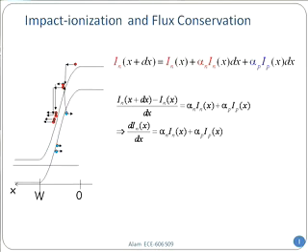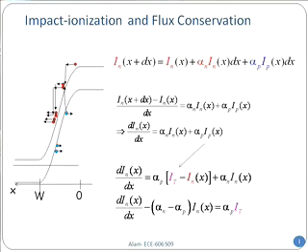So for example, the electron current, remember this is steady state. There is no derivative term for time. In steady state, the current must be continuous. Whether you look at it in the right hand side, in the middle, or in the left hand side, the total current, sum of the electron and hole current, must be continuous. And that total current, if I call that total current I sub t, whatever that current is, I don't know yet. If I call that current I sub t, I shouldn't carry around an x with it, because it is independent of position. And since the current must be conserved, the hole current must be written as It minus I sub n. Now this is only in steady state, of course.